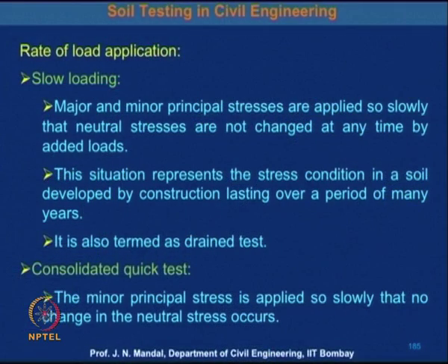Another is the consolidated quick test. The major principal stress is applied so rapidly that neutral stress carries all the additional stress. This is known as consolidated undrained shear, which can be designated as CU.